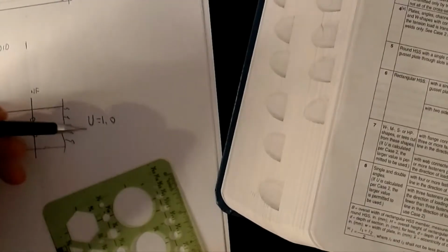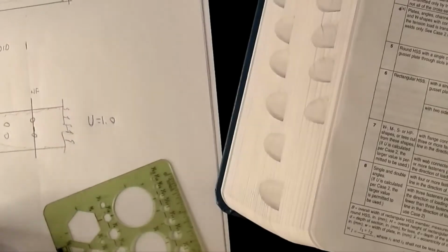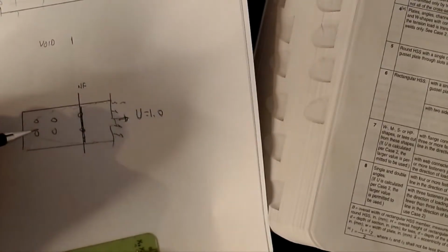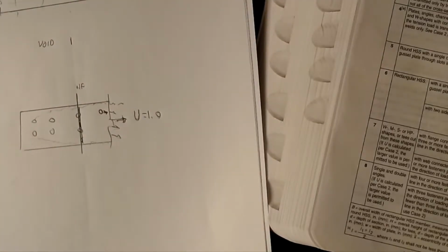There is no reduction of the net area when I calculate my effective area. In fact, this was the case that we did in our example 2 videos back when we started talking about the net fracture definition in general. You can see that pretty much the entire area is being loaded by the way the loads are being applied. Now, again, this assumes that the load is over the entire cross-section, which means my point load is acting at the centroid. If my point load were acting up here, then you start getting into some dead areas. If it was a load applied by, say, a bolt that's off here, and we're pulling on something like that, you've got to be careful on that definition. That's why it's important to understand how these forces are flowing through things. But that's Case 1, when it's safe to think that every element in the cross-section is being used to help with the load.